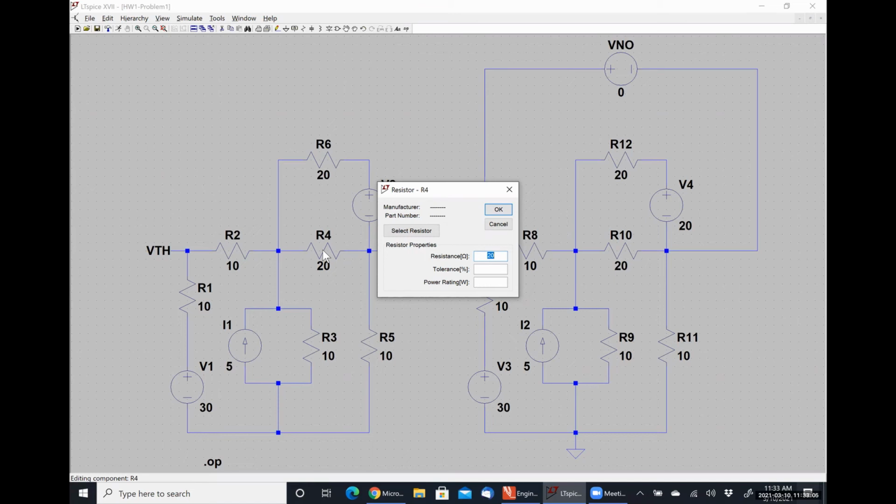And then the color of the resistor itself usually tells you what the power rating is. So if it's tan, it's a 1/4 watt. If it's kind of a light bluish green color, that's usually an eighth of a watt. Anyway, you can simulate all that in here and see whether or not you're exceeding the resistor's power handling capabilities, to see whether you're going to burn stuff out. So we're not going to use nearly all of these practical functionalities in this class, but again, it is a very, very powerful tool.